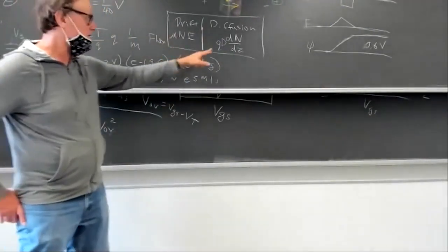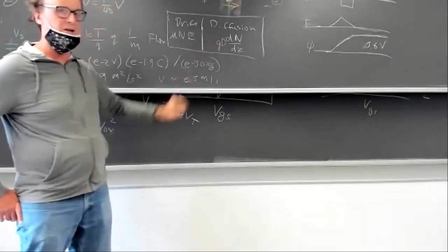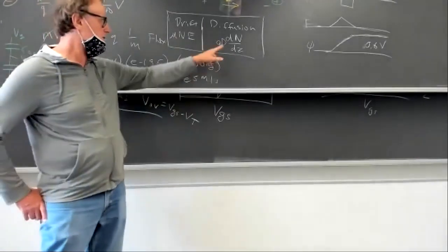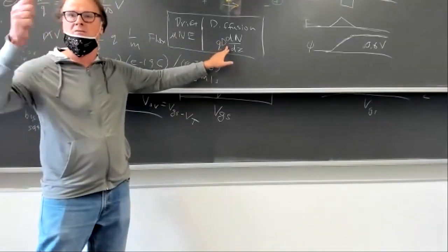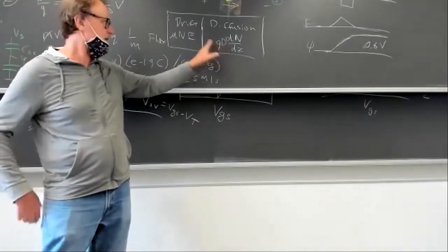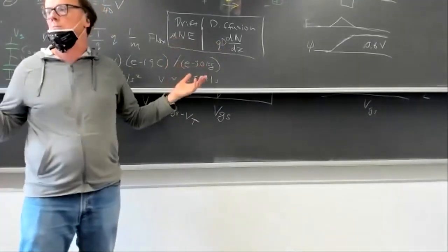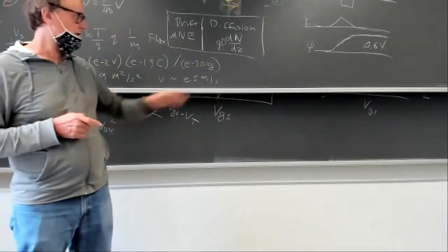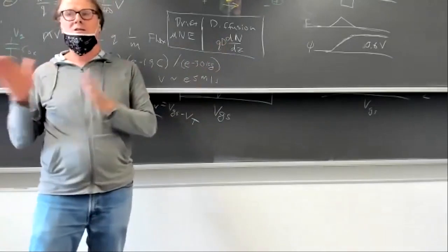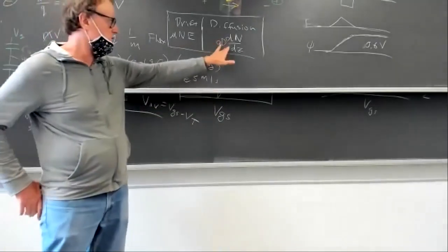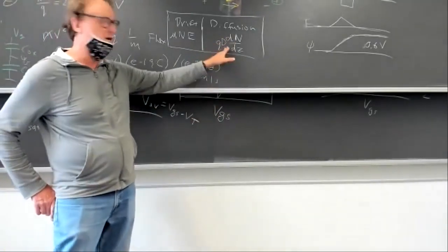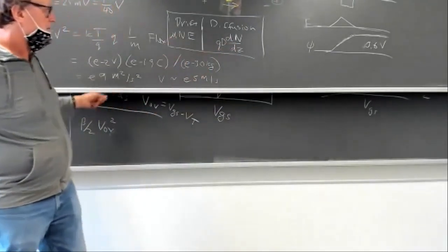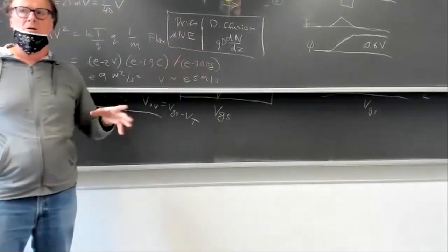Why should the diffusion constant depend on temperature but not mobility? It's very obvious why that is, right? Diffusion increases with temperature because the hotter it is, the faster things move around. Of course, that doesn't affect how the carrier is moving to first order due to the electric field. You never actually use this. It's just to be aware that diffusion is proportional to absolute temperature somehow, and mobility is not. But both are a function of temperature.